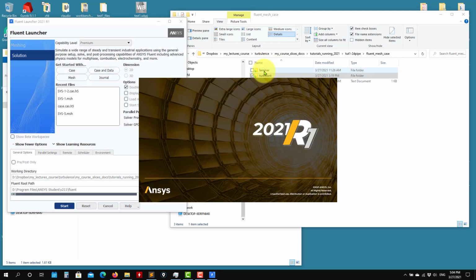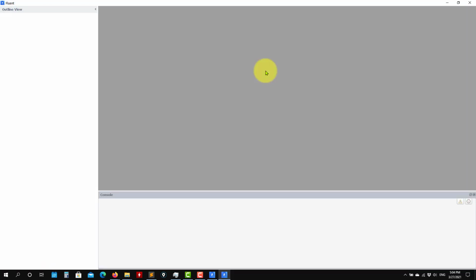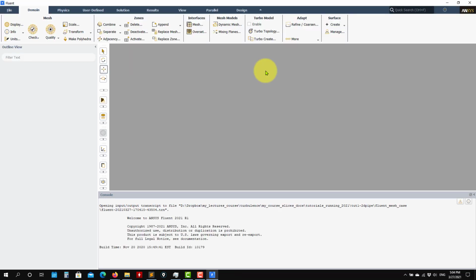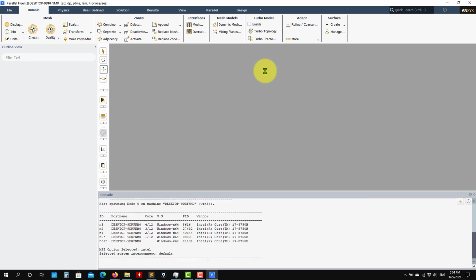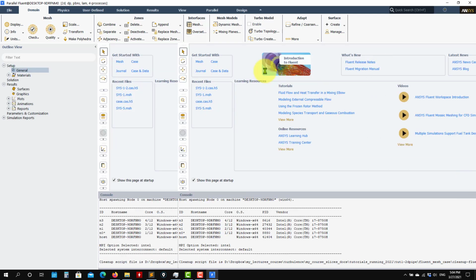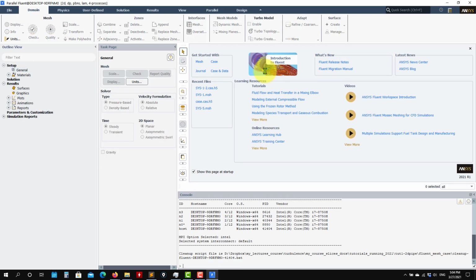What I was telling you is that when you run a laminar case, my advice is do not use a turbulence model. If you are 100% sure that your case is laminar, switch off your turbulence model. It is less computationally expensive, and sometimes the turbulence model might add a little bit of that black magic, the turbulent viscosity. So you might get some slight differences between the laminar solution, where you have an analytical solution, and the one when you enable the turbulence model. So be careful. That is my advice.